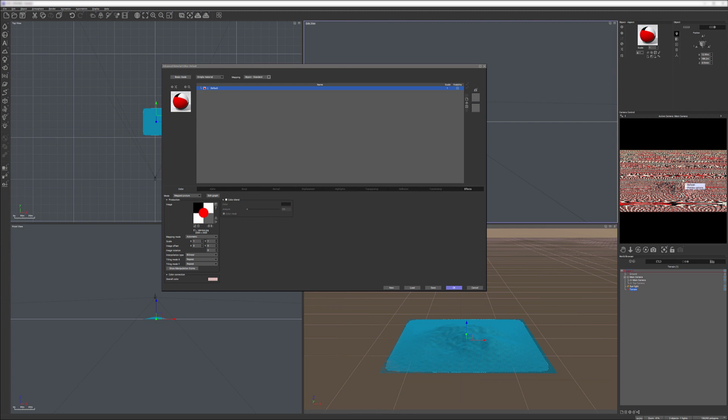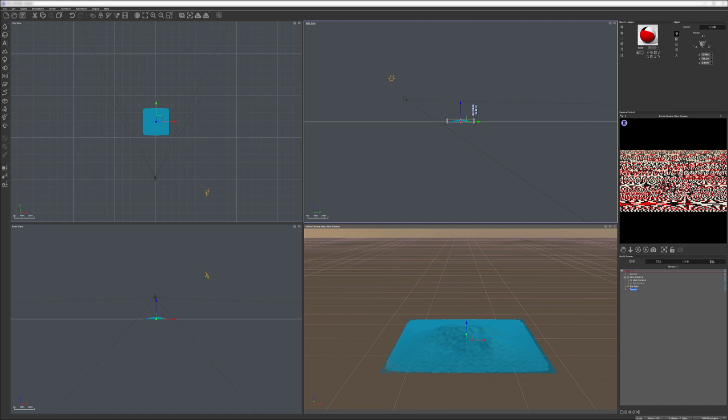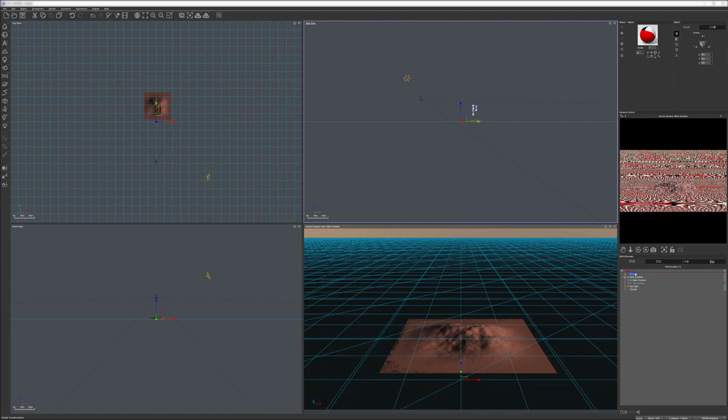Matching mode is kind of important if you try to take an image and apply it as a mapping mode or any other mapping mode, and you want to be sure your overall terrain and multiple background mountains match together. You maybe want to switch to the world standard or world parametric type of mapping. So in this case, all these scales and everything is matching. So speaking about that, sometimes we don't necessarily need to match them.